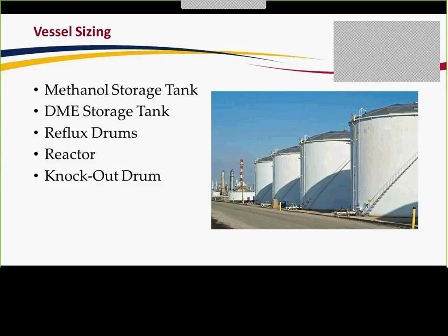For the reflux drums, we placed these following the condensers at both the water and the DME columns. To size these, we wanted to ensure that we were keeping our liquid seals on the pumps following these. So we considered a 5-minute hold-up time and the mass flow rates to determine the overall size of the reflux drums. For reactor sizing, we assumed that the lengths and diameters provided by the HYSYS model were accurate, and then simply added the wall thickness to the reactor dimensions.